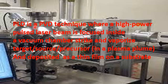So pulse laser deposition is a kind of physical vapor deposition process in which a high power pulse laser beam is focused inside a vacuum chamber, and that focused beam strikes and vaporizes the target or source or precursor material. This vaporized material is then transported and deposited as a thin film on a substrate inside the pulse laser deposition chamber.